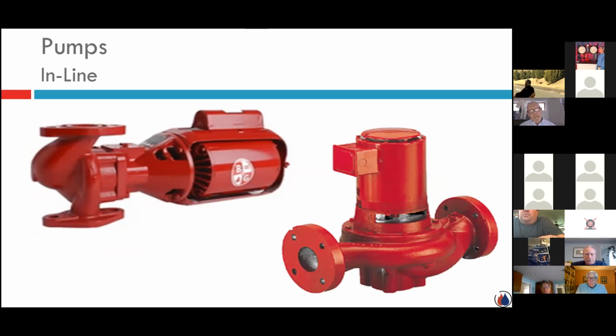As you get into some of the larger size pumps, meaning larger capacities, larger flow rates, greater pressure differentials, you can have the inline family of pumps. And then sometimes in these inline pumps, you can have what they refer to as a three-piece pump. The three pieces being the volute, the wet end of the pump, the bearing assembly, which is the connection between the motor and the impeller, and a coupler that connects the shaft of the motor with the shaft of the bearing.